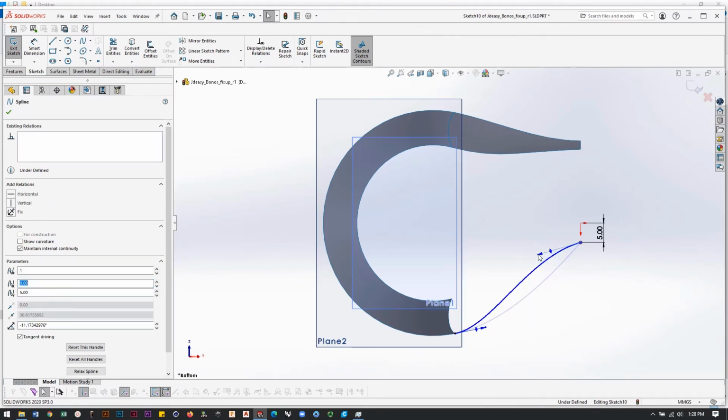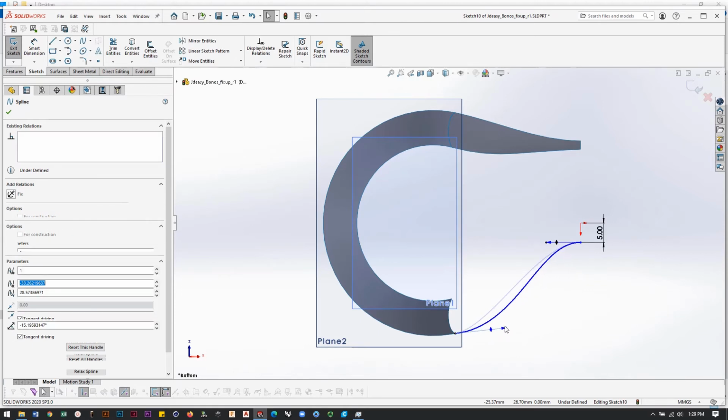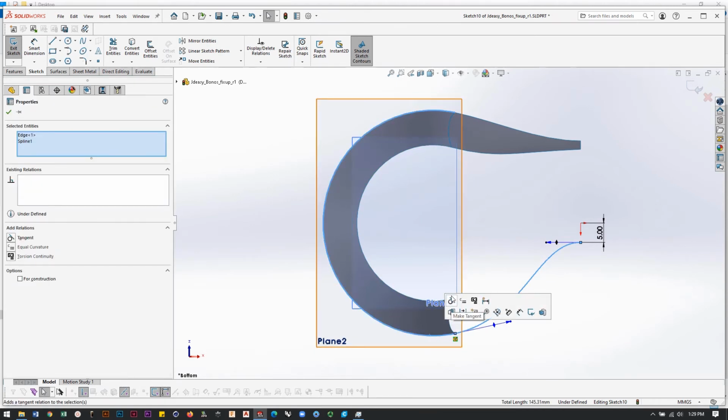This curve is the problem curve. This bottom front edge seems to be where all the drama comes from on this build. So we're going to set this thing up to be as massaged as possible, but we're going to be aware that it's a problem curve and we might need to come back to it at a different point. So I'll click the main part of the curve, and I'll click this edge here with Control held down, set tangent. And you saw that very subtle little maneuver there.